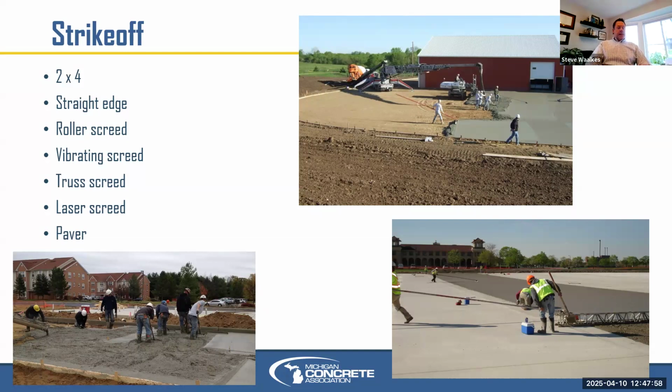But anyway, those concerns aside, as far as thickness, minimum 4 inches. And once you get above 6 inches, you don't get any benefit in the concrete from the thickness design or from additional support offered. Generally, I'd say 4 to 6 inches of 21AA, of either gravel, crushed limestone, or recycled concrete, in most situations, unless you've got some unique loading and heavy loads.